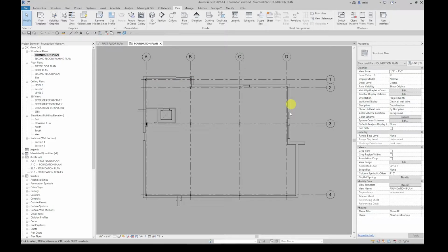So that grade beam is a very unique thing to this drawing. It's not going to be something that we want to reuse again in any other building information model, because it's going to be transitioning to these different shapes as we change these walls. So for these unique elements, we are going to use an InPlace family.